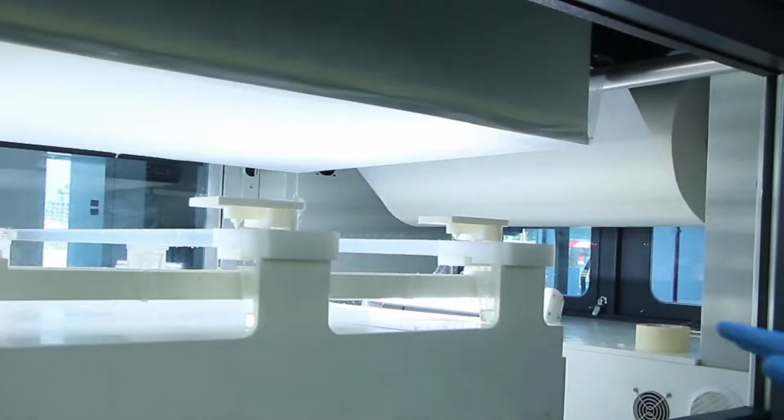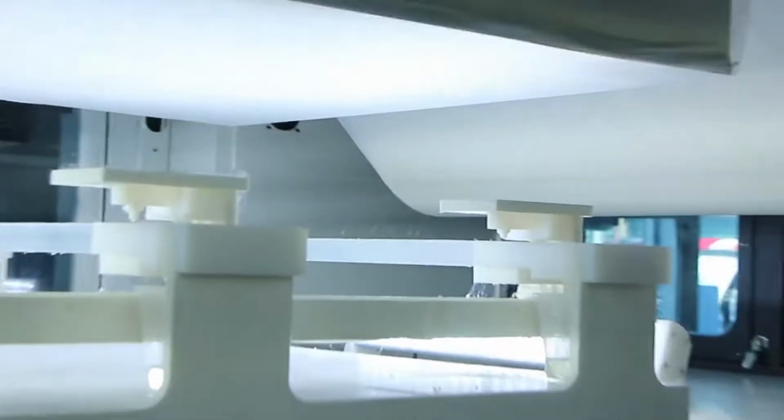When we have properly stabilized the process, we'll go back to the graphs and show you how the pressure difference is changing now that we are coating our substrate. Now we're adjusting the negative voltage, so the collector also, you can control its negative voltage to improve the electrostatic field strength. We have to be careful from there. All right, so now the coating process has initiated.